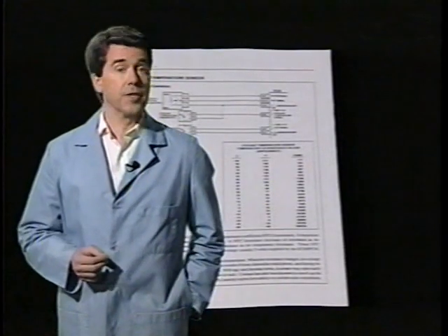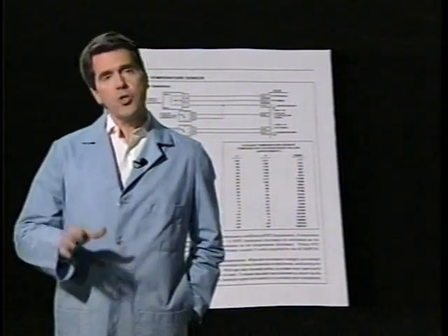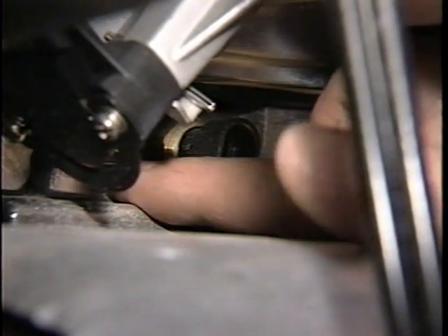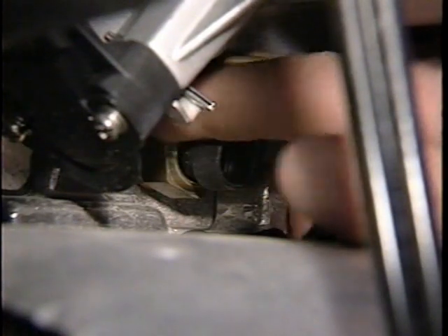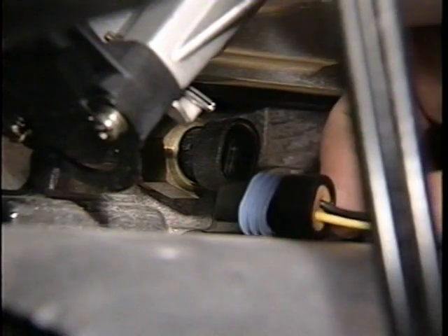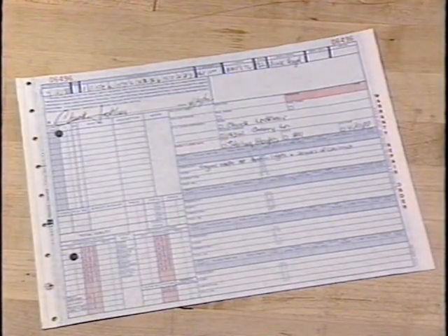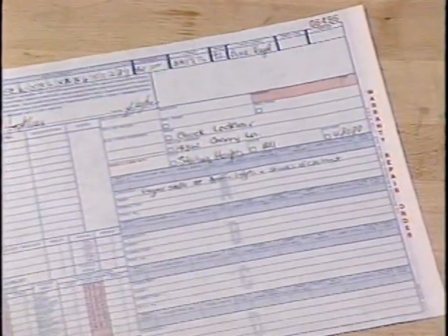driving. Other unique sensor failures that can cause drivability problems are also listed. For example, you should also unplug the coolant temperature sensor and look for coolant leaks. Coolant has been known to travel up inside the sensor connector and into the wire. Eventually, it migrates into the ECM-PCM, resulting in engine drivability complaints caused by terminal corrosion. Coolant odor complaints in the passenger compartment could also be possible.